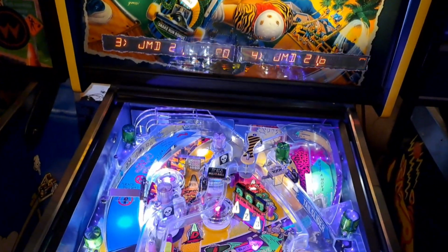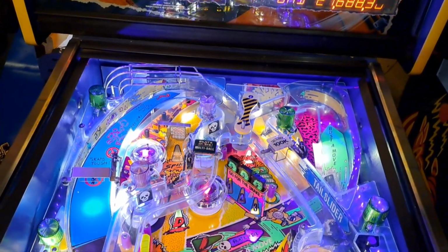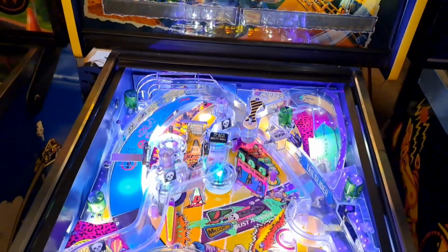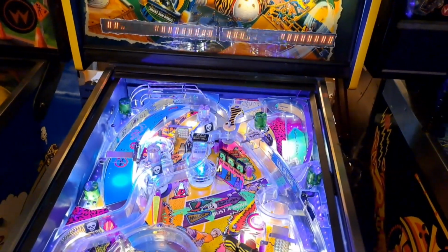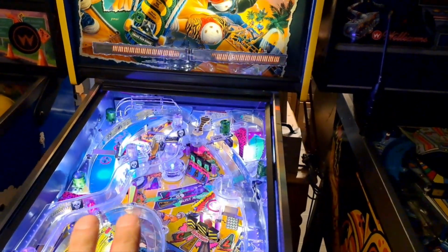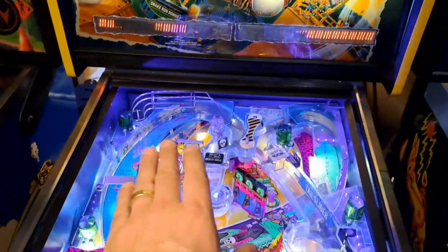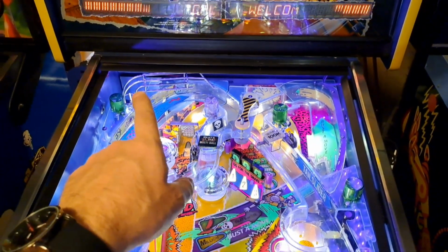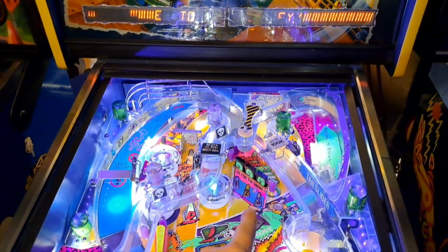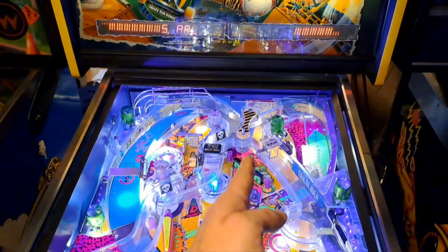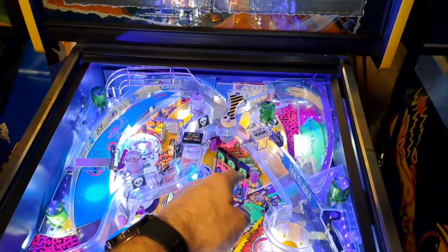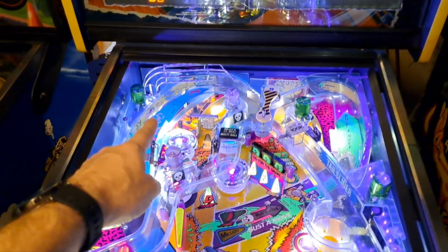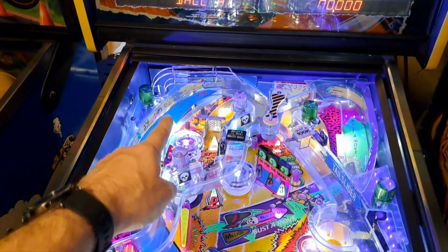And recently I installed this vertical upkick assembly. You might have seen the video. Pretty awesome mod. I love it. But almost immediately I had some feedback on Pinside about it saying, hey, the only problem with doing this is if you get more than one ball in that snake run, the machine will only fire one ball out when the drop targets come up. And of course, the other situation might be if you sneak a ball in there right as the drop targets get reset, the ball will fall, land over here, sit on that VUK, and won't go nowhere.